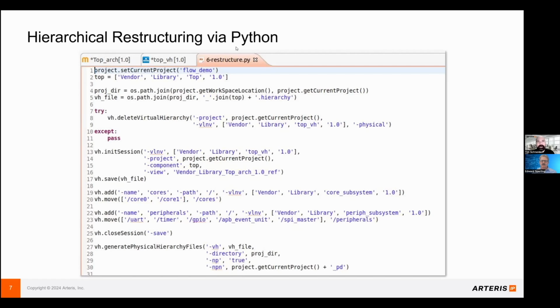And it lets you also spin derivatives quickly. So say I've got one, oh, now I've got this new block of IP. This version of the design is going to have a greater ALU matrix, or it's going to have additional interface peripherals, wireless versus Bluetooth versus near field communication. You could bring those blocks in and you can configure those parameters and easily plop those in with IP-XACT and manage all that.